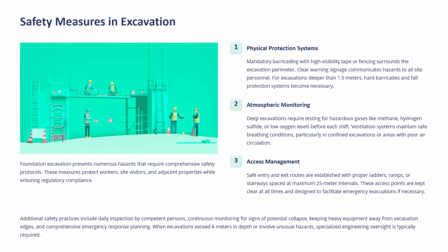For atmospheric monitoring, deep excavation requires testing for hazardous gases like methane, hydrogen sulfide, or low oxygen levels before each shift. Ventilation systems maintain safe breathing conditions, particularly in confined excavations or areas with poor air circulation.